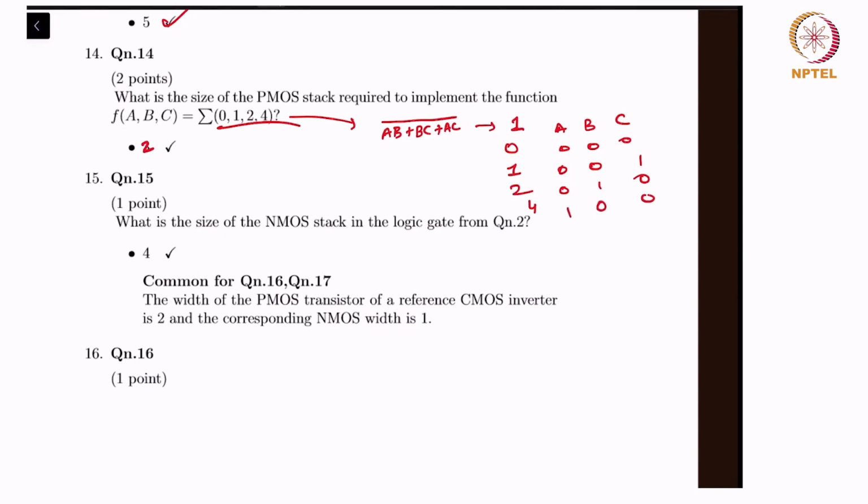And if you notice, I'm sure sir would have said this, if the function is a self-dual function, as in if f is equal to f dual, it's possible to implement the function quite minimally, right? You can just mirror, both stacks will be mirror images of each other, so whichever stack requires the lesser size implementation, you can just use that and mirror it on the other stack.